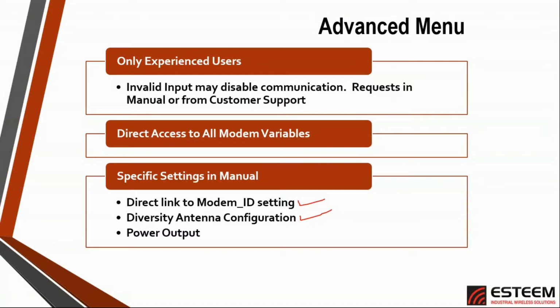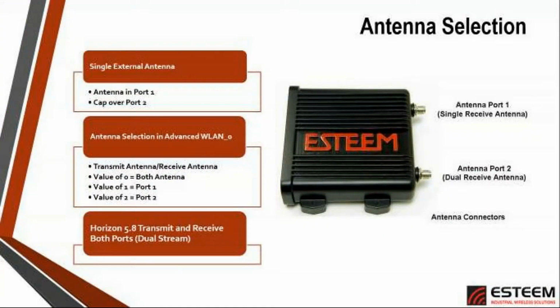And the other thing that may need to be adjusted is actually the output power in the radio. The output power in the radio is always shipped at maximum power, but if you're in a very low distance application, putting it at max power, you may be causing your own interference. So you may need to adjust the power level to get your signal strength down to a point that it is within acceptable values between the radios. So let's go ahead and take a look at a couple slides that I'm making reference to.